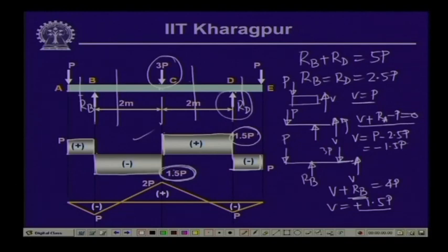as we get. And as you can see along the length of the shear force diagram, we have 3 places where the shear force has changed sign from positive to negative or negative to positive. So, at these 3 locations we expect that there will be values of the bending moment which are maximum in nature.